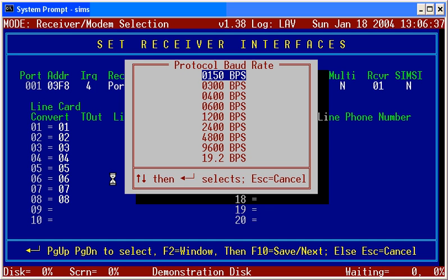If you choose very high speed protocols, there's the chance of overrunning UARTs, some of the computer UARTs out there that actually receive the universal asynchronous receiver transmitter in. They may have buffering in there of 2 characters, 1 character, 16 characters. So if you keep the speeds down, since the SIMS2 deals with these under interrupt, the chances of ever having a problem are very, very remote.